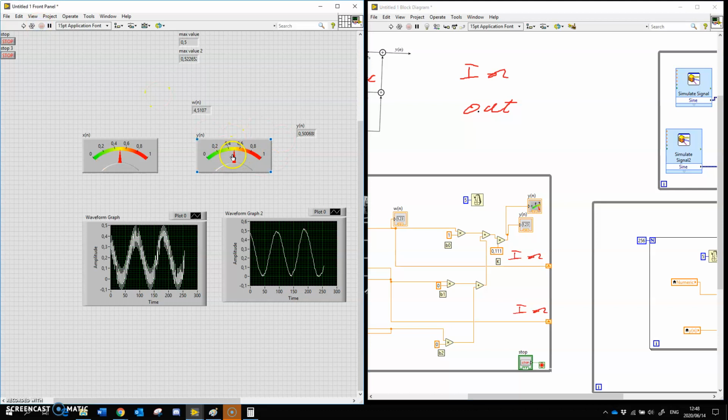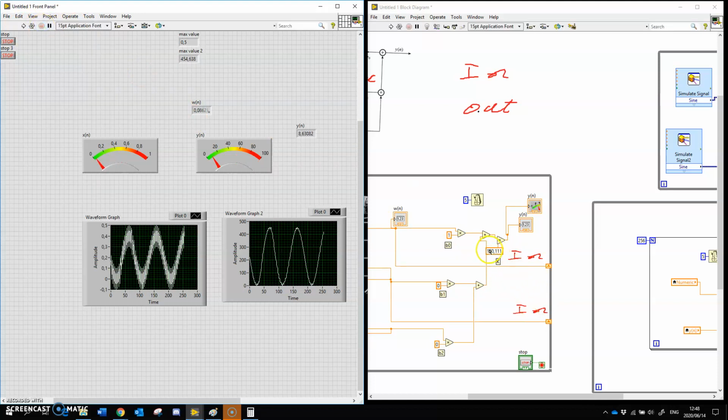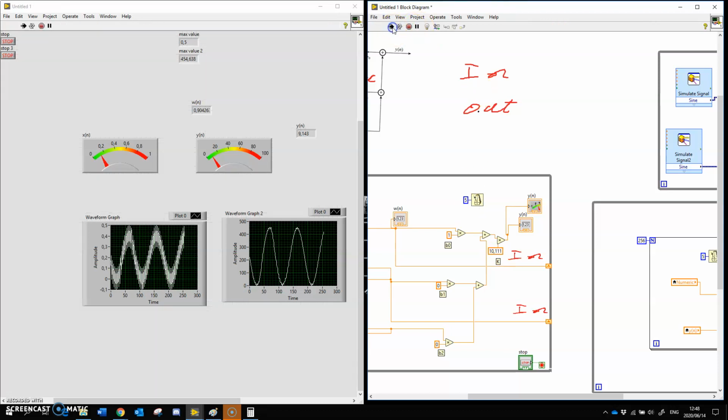So if you want that one not to show 0.5 or 0.4, if we multiply this with 100 and that calibration factor, and we change this to let's say 100 degrees Celsius, then it's going to run from, oh, I've done too much, sorry, 10. There we go, sorry, not 110. See, now this is in degrees Celsius, so I've calibrated that to show in degrees Celsius.